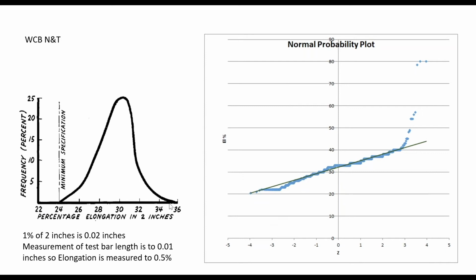And I really have 2 different sources of this distribution. One is the inability to measure exactly the same piece of steel twice and get the same number. That's test uncertainty. And then I've got variability in the material itself. Since I broke that bar, I have to use a new bar, and that new bar comes from someplace different, and that different location will have slightly different mechanical properties.